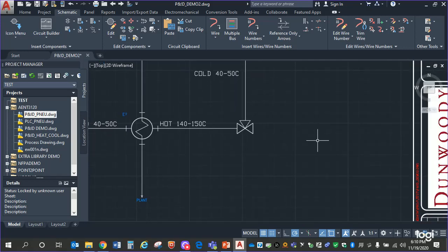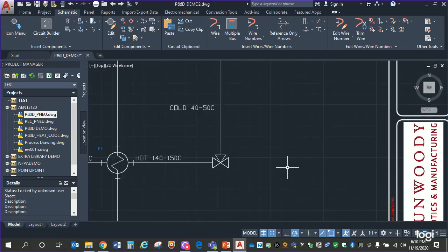So I can see coming into my three-way mixing valve, I've got two temperatures of water. I've got 40 to 50 C, and I've got 140 to 150 C. That means I can do almost anything now, right? I can mix that up in any way, shape, or form. And what a three-way mixing valve does, a lot of these, you can adjust them. Or if it's truly a three-way mixing valve, I could actually adjust it in the middle. So I could take half and half. Right now, if it's exactly as drawn, I've got half 40 degree water and half 140 degree water. I'm going to get some sort of mix out of that that's in the middle somewhere, right?